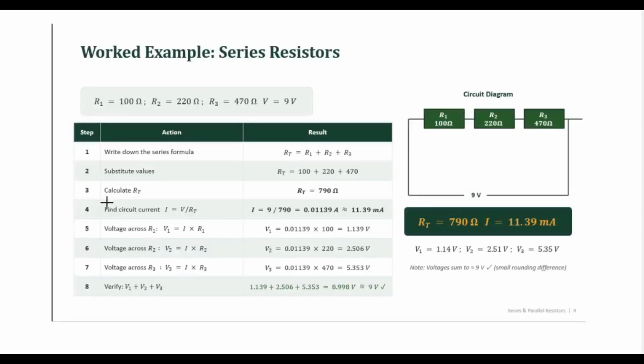Okay, let's take a very simple example to explain this point. You have 100 ohms, 220 ohms, 470 ohms, all arranged in series as shown. Let's write this symbol very well. That's the battery symbol. This is going to cause current I to flow in this circuit. And because they are in series, the same current is going to be flowing through them, no matter what.